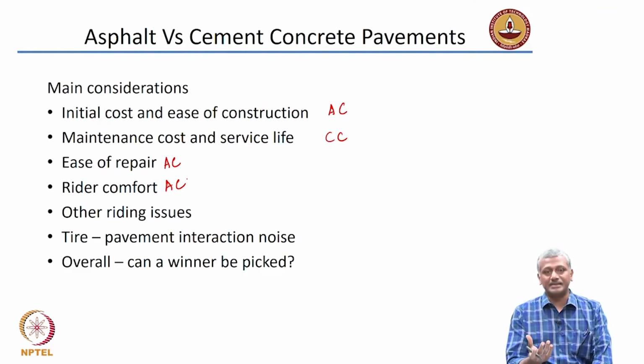When you are driving in the night, the asphalt concrete pavement which is black may not really have the reflectivity, unless of course the polish on the surface is good and the aggregates are able to reflect some light. That is why you need to provide all those markers or indicators to ensure that people are moving in the right lane. Concrete pavement, on the other hand, reflectivity is better.